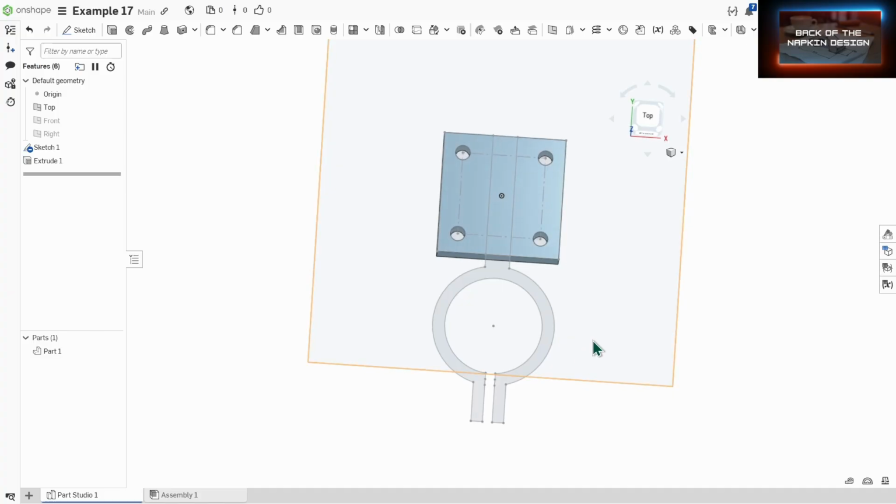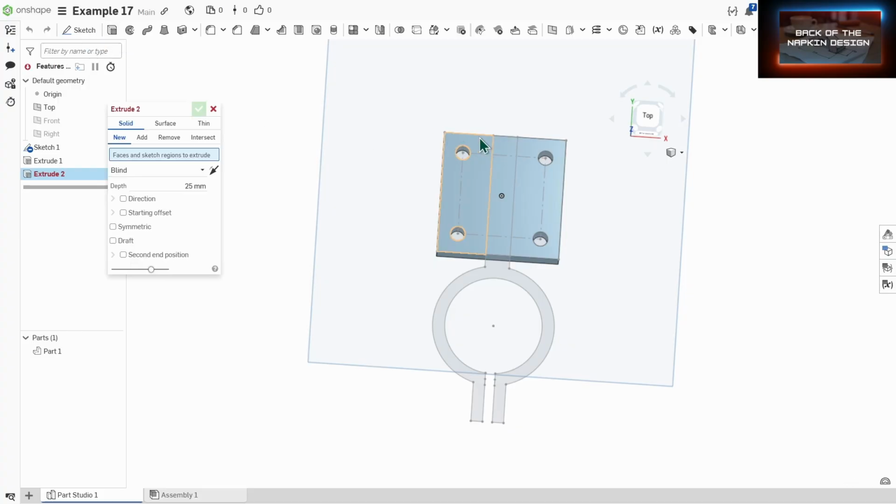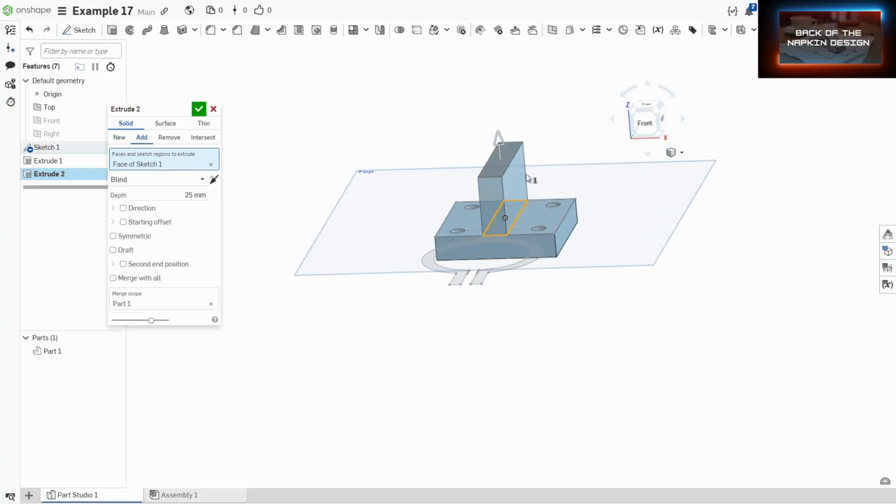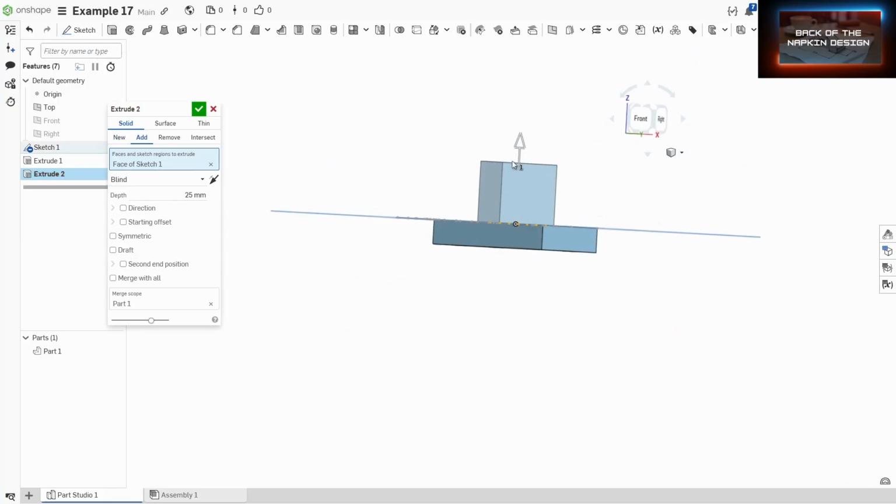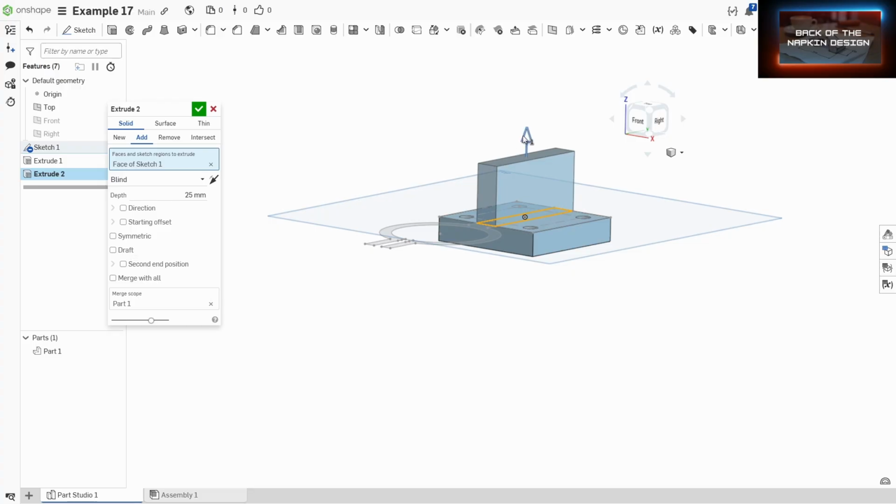All right, so I'm going to rotate this. Now I want to extrude this one here. And first I can extrude this, so I'm going to do extrude, grab this here and pull this up. This is going to go up 60 millimeters. So we're going to go over here, change this to 60, enter. I'm sorry. We're going to change that to 50 millimeters because of the 10 millimeters including this. So 10 plus 50 equals 60, and that's the dimension.